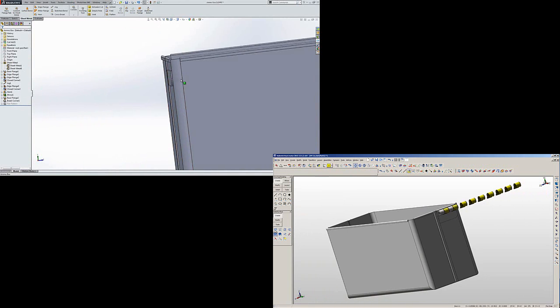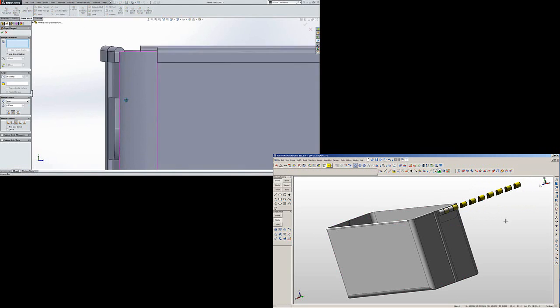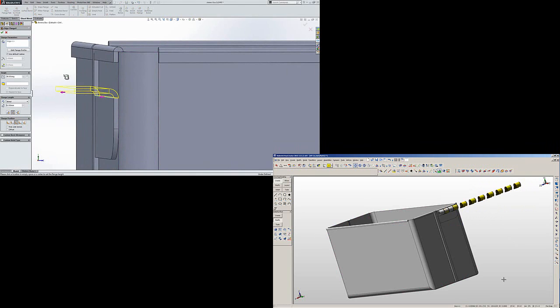Normal to, the face that we want to sketch off. And what we're going to do is create an edge flange. So edge flange, we're just going to select this edge and extend outwards like so. Now the dimensions that we're going to apply are going to be this internal radius, which is fine. We're going to have a degree of 50, just to angle it like so.